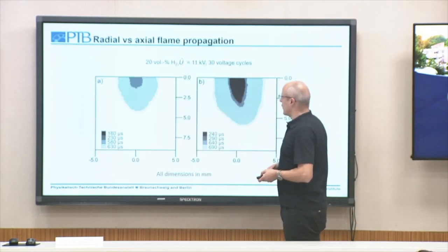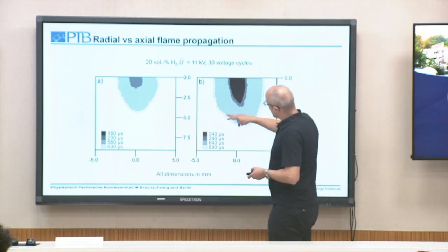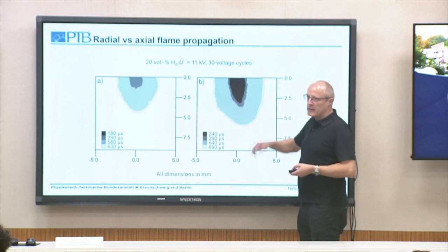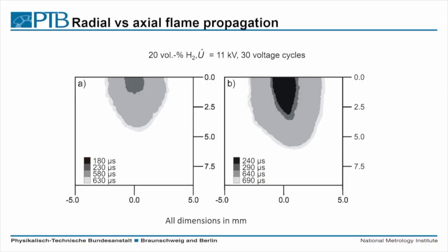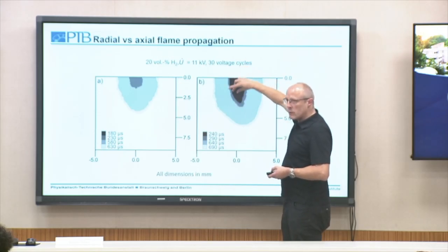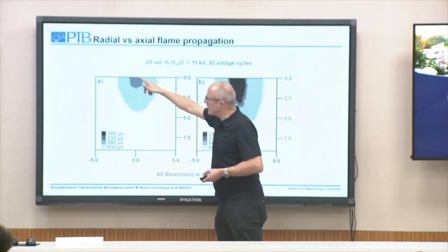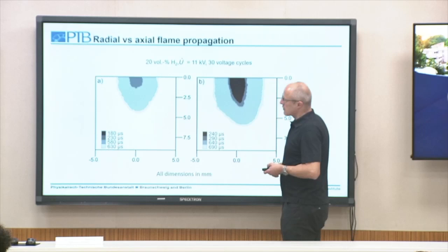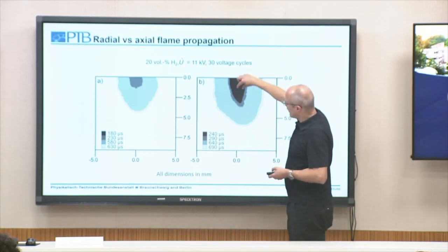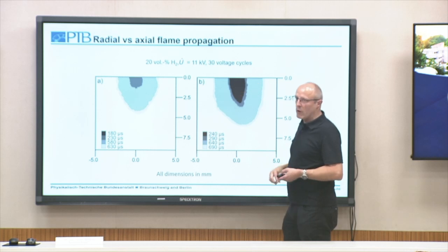There's one problem with, maybe problem is not the correct word. So you see this non-spherical shape. Of course the streamer discharge occurs along this axis. So there was something like a preheating here, and even though we may ignite only here at the tip of the rod, of course, we do not have quiescent unburned mixture along this coordinate anymore.